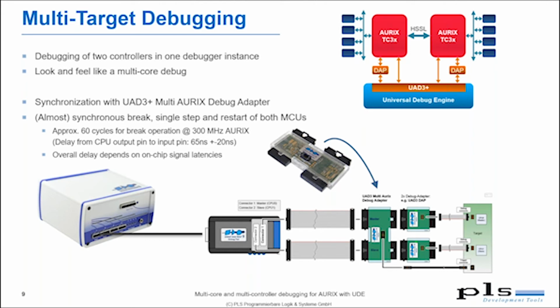And for these two use cases, we offer a special feature that allows you a synchronized debugging of both AURIX MCUs. As you are already used to from multicore systems, the entire system, that means both MCUs, is debugged within a single debug environment.